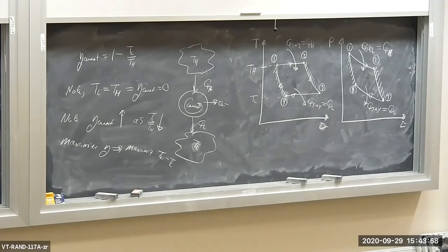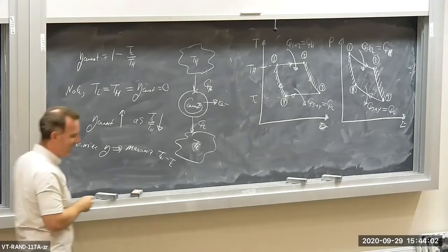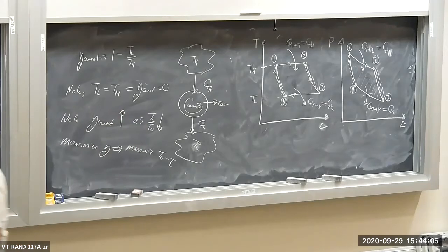So air, if we apply any kind of conservation relationships like the energy balance, the air inside the piston cylinder device is going to be our system. Okay? So you have a Carnot cycle, air is the working fluid or the system. The heat transfer to the low temperature reservoir during the cycle is 3.4 kilojoules. The high and low temperature reservoir temperatures are 300 and 250 degrees Kelvin.